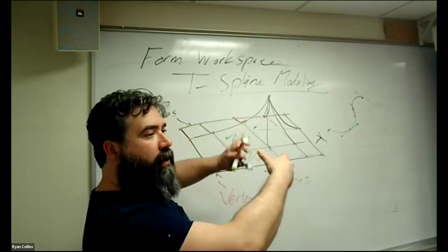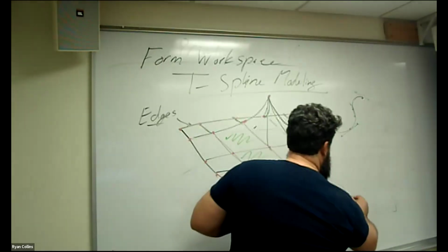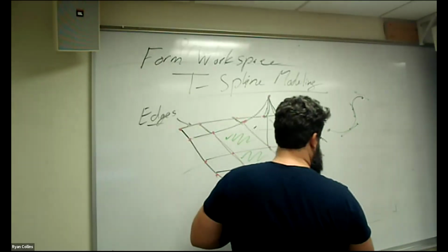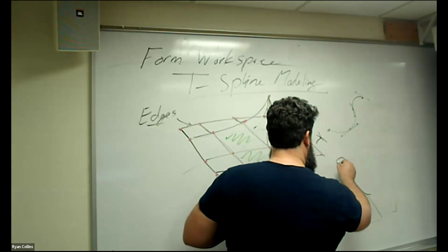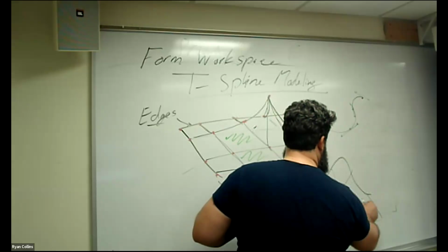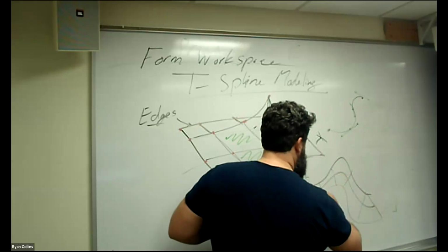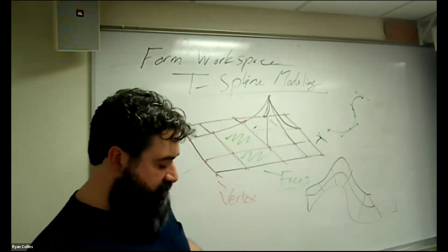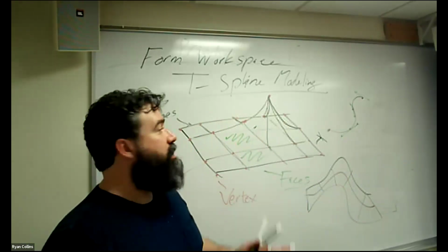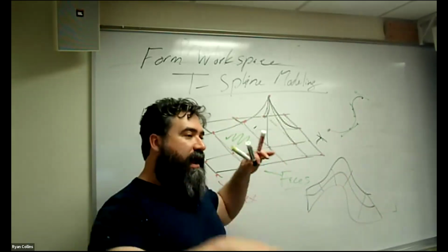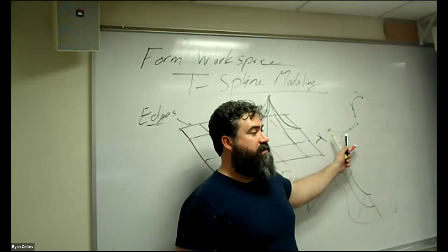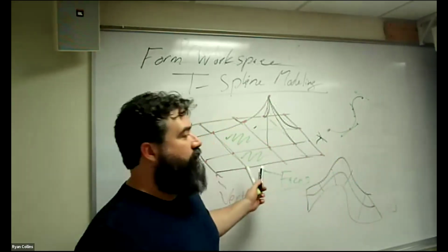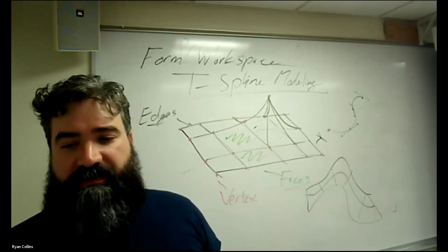So no matter if you take this whole shape and turn it into a morphed, I was going to say Pringle, and then I went a little bit too far with it. But this whole thing can be morphed, everything in between, but it's all going to interconnect. However you decide to alter that, it's all going to interconnect. So this T-spline modeling means everything is interconnected, just like when we've been working with regular fit point splines. So how we work with this is first we go into the modeling workspace. So let me switch over to Fusion.